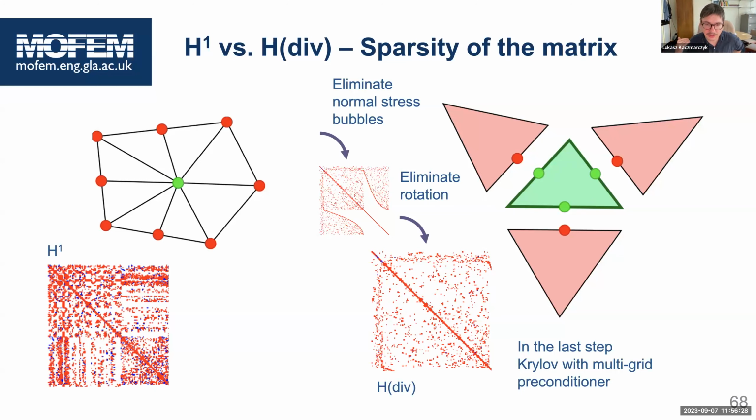So if I want to push the efficiency of my system to the very end, I can harvest that property, because a priori I know how much memory I need without looking into the adjacency of my mesh. I have to look only at how many elements I have. Here, I will have to construct the structure of that matrix. To know how many non-zero elements, I have to go over every node and check what is the adjacency. That can be a costly thing.